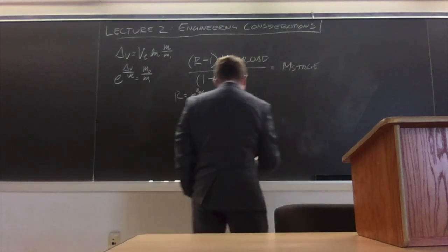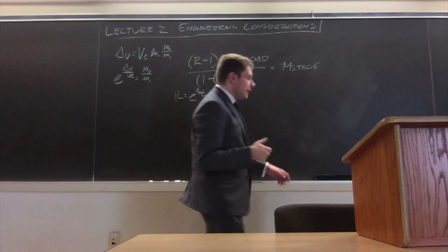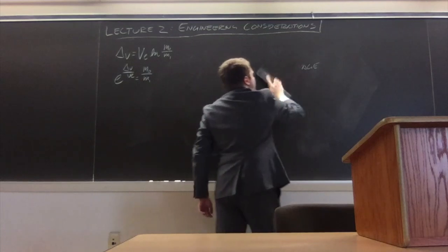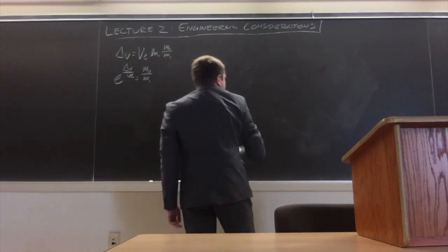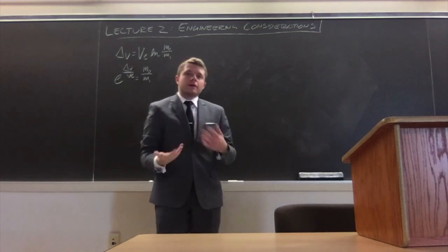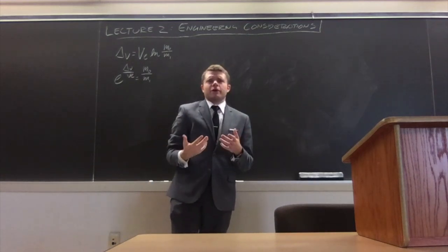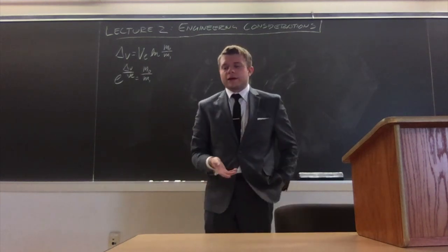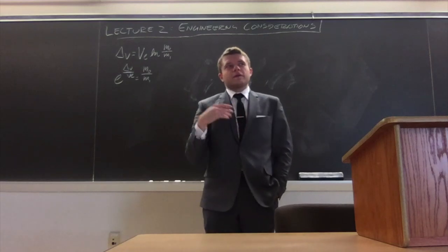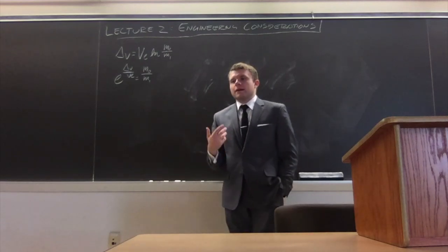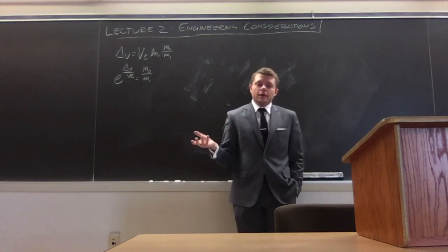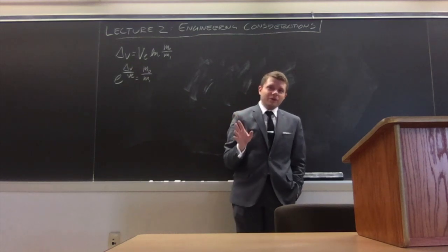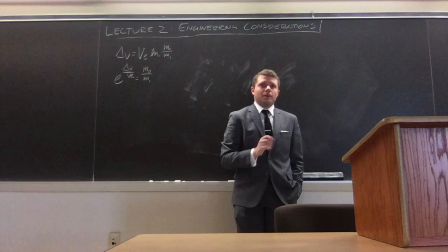But the fundamental principle that I've discovered in my own work, and I'm 90% sure this is an actual thing, is that to optimize your vehicle, you basically want to build the smallest possible vehicle for a given job. Because everything that goes into the total mass of the thing is in some way, shape, or form a direct function of cost. In fact, I found in some research I've done on my own time that you can almost directly predict the cost of a launch vehicle by taking its inert mass and multiplying it by $4,000. And that will generally, as a rule of thumb, give you a good impression of how much it will cost to build an orbital rocket.